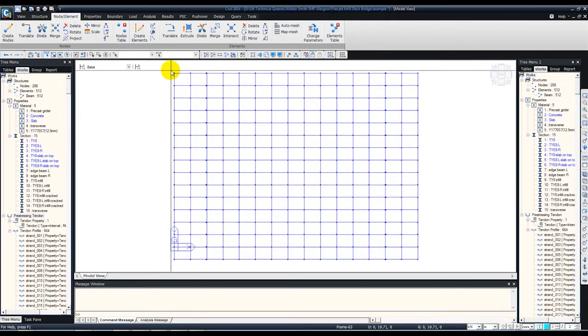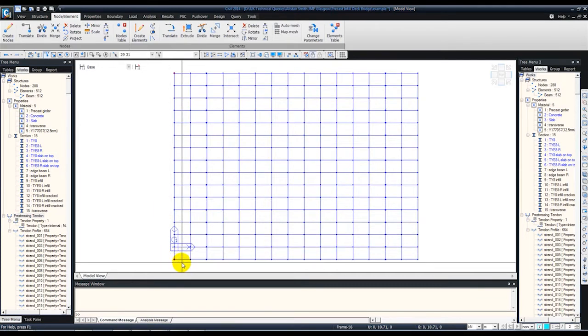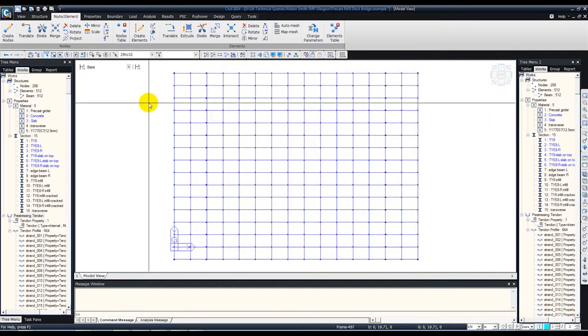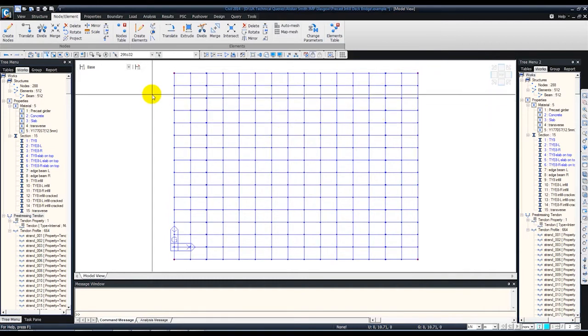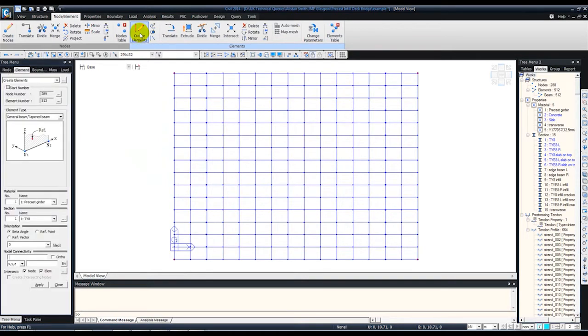the bounding area of the abutment, the lines, the outlines of the abutment. So just selecting the cornermost points like this, and we'll create lines out of them. So create elements, extrude elements,